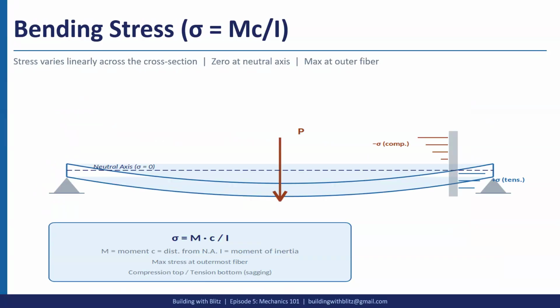So bending stress is where we get into thinking about beam design or retaining walls. It's anything that's going to be caused by a moment. So you can kind of see it here. These graphics are kind of not very well made, but bending stress is when we have a part of the cross section that is in compression and another part that is in tension. Where the compression and tension, there is no internal force or equals zero, is defined as the neutral axis.